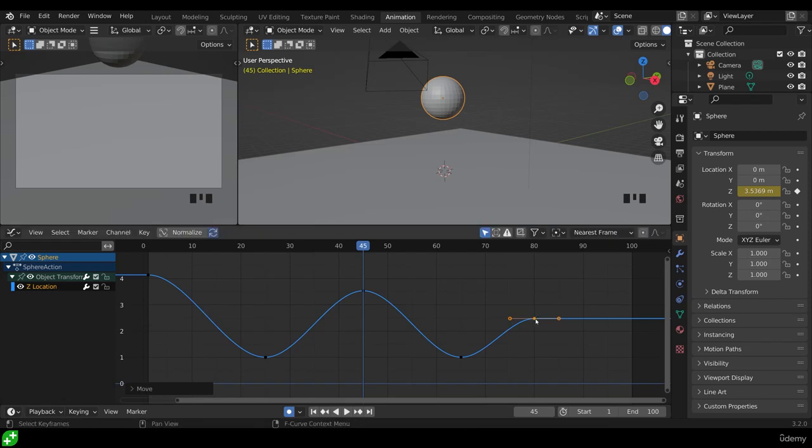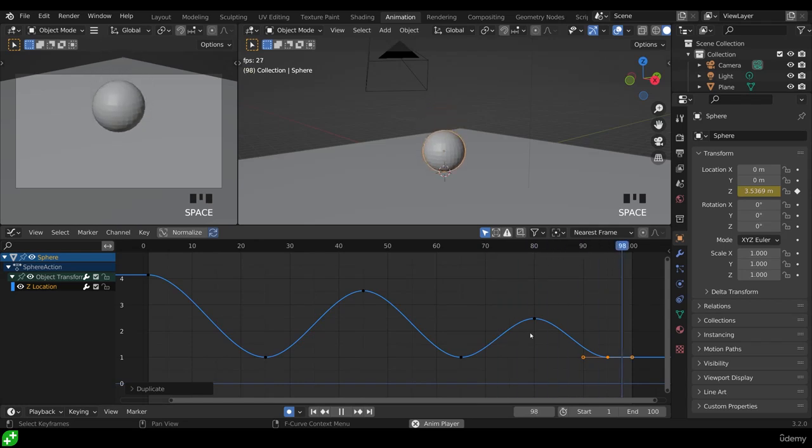It doesn't matter if you've got different heights to me. We can change this all in a moment. And then I'll duplicate this one, Shift D, in the X, move it across, and again, another 15 frames. And let's just see what that looks like. So I'll press play. So it falls down, bounces, and bounces again, and dies. And the bounces stop. It doesn't look much like a ball bouncing at the moment. But before I continue, pause the video here and catch up with me, making sure you've got a similar bouncing ball to what I have here.